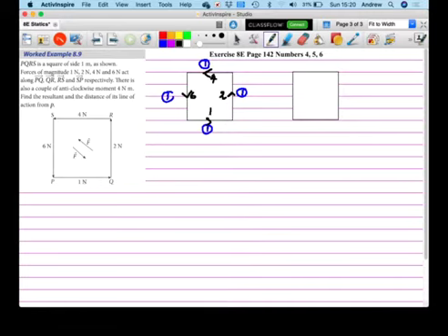Now the other interesting thing about this, and you need to be very careful with this, is that there is a couple. And the couple has a moment value of 4 Newton meters in the anti-clockwise direction. So I am now going to put the couple in red, and I'm going to write it using moment notation. Basically what I'm saying is there's no overall force up and down.